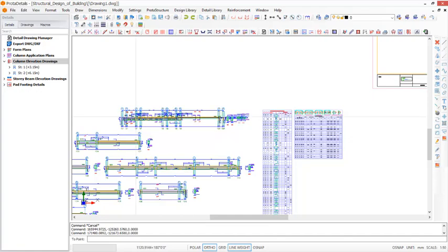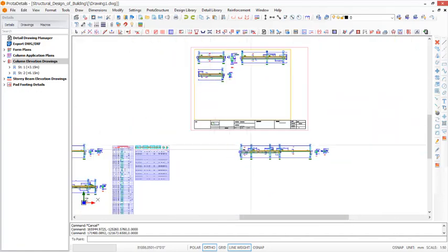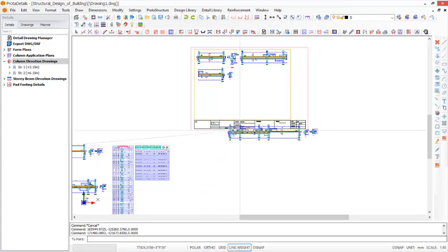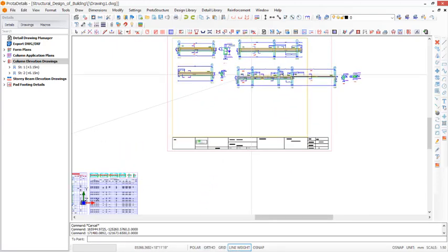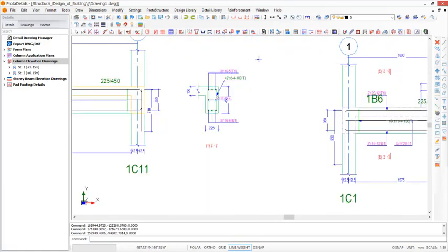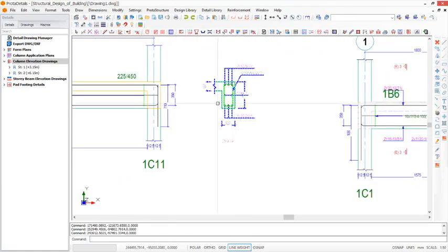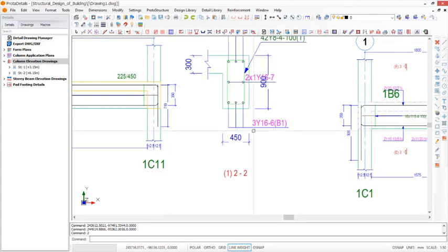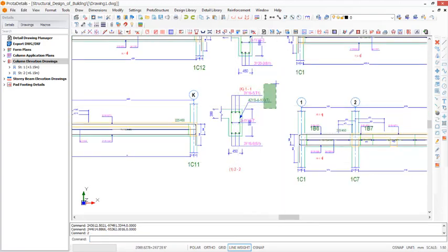Move this drawing all the way into this title block. We are going horizontal because auto is activated. Let's deactivate that. Come over to these provisions to place these drawings. The reason why I'm trying to place it right here is because we need to increase the scale of this particular drawing. So let's see. Scale, pick this first point right there, and then come to the provision, key in 2 right there, and enter on the keyboard, to increase the scale of this drawing.